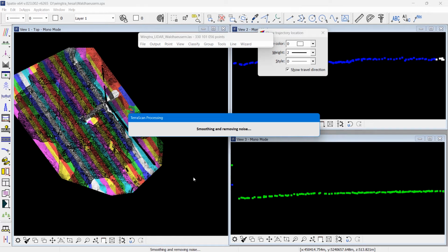The smoothing is an operation which modifies the X, Y, Z of each point. If it looks like there is a local surface, and a small change to the X, Y, Z of the point can make the point match the local fitted second degree surface nicer. We should see the effect of smoothing in the cross section view windows. The cross sections will become cleaner lines, the image of the point cloud in the cross section.